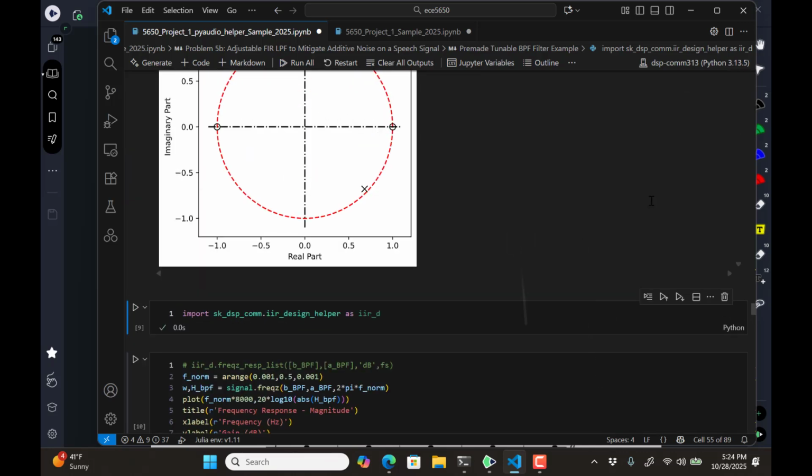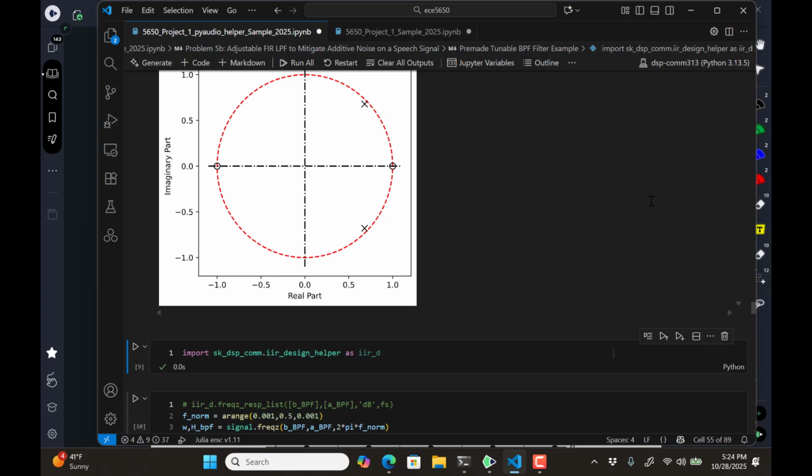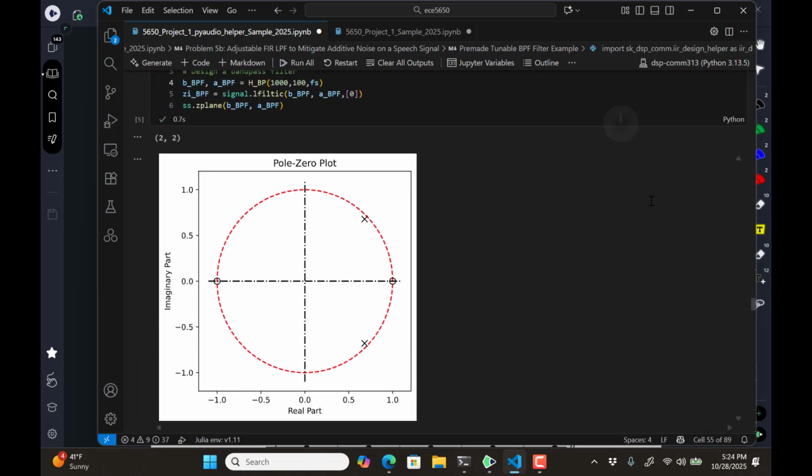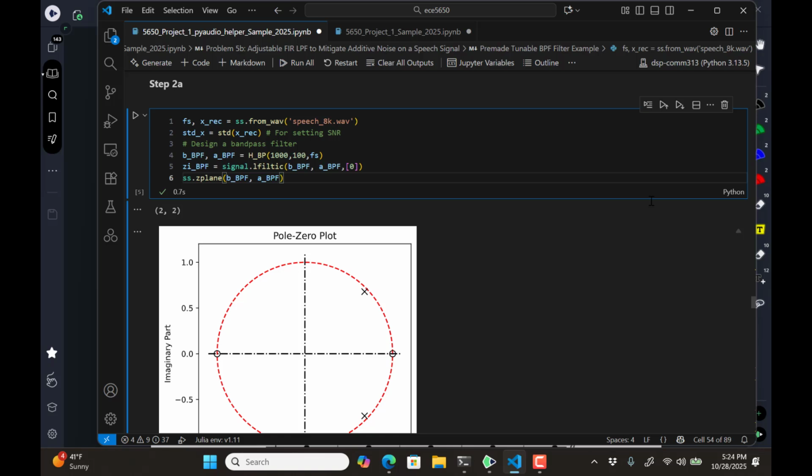And there's another piece of code slipped inside of here, which is not so obvious at first, but we saw this when we were talking about continuity and initial conditions. That ZI bandpass filter is calling lfilter with initial conditions. The filter is designed in the line just above that, and then I create an initial condition vector based on the size of that filter. So you'll do something very similar for your filter, which is 32 taps or whatever length I wanted you to make it.